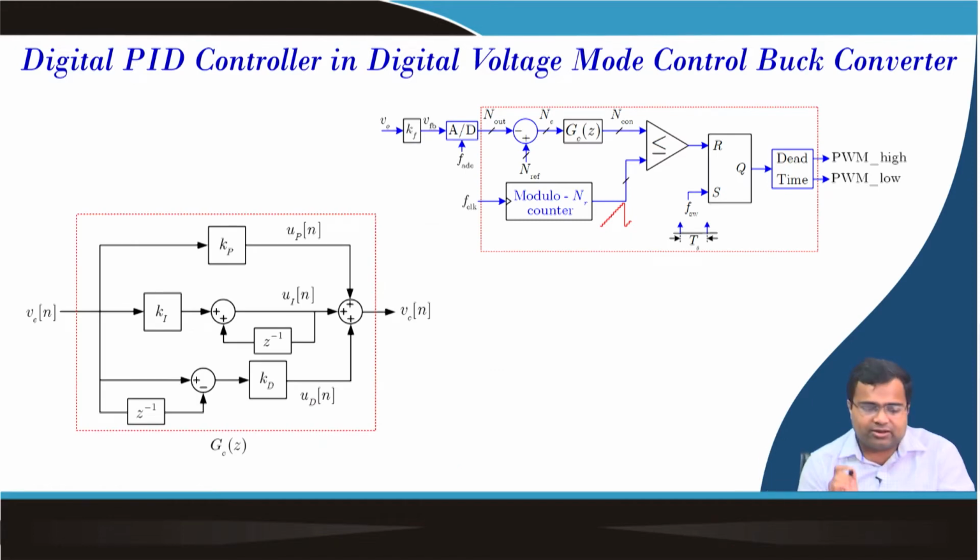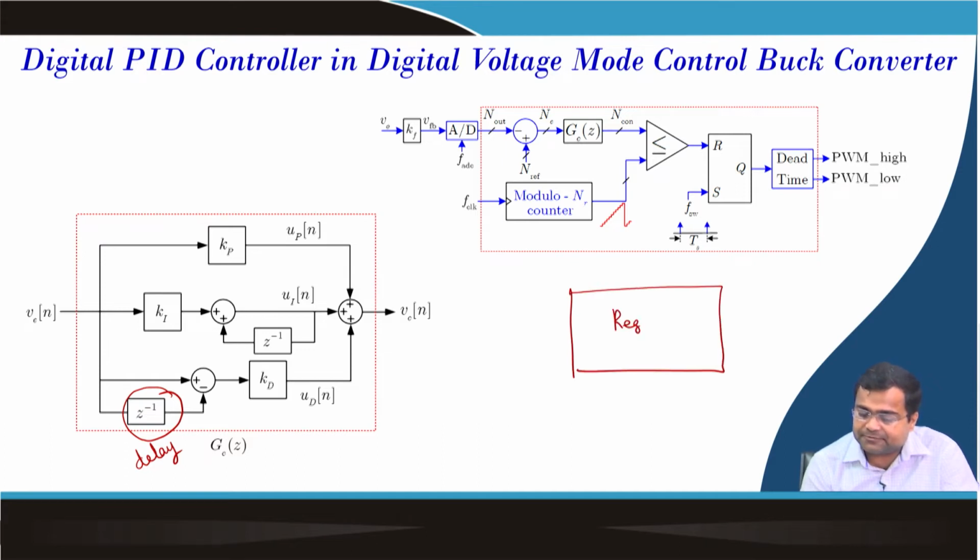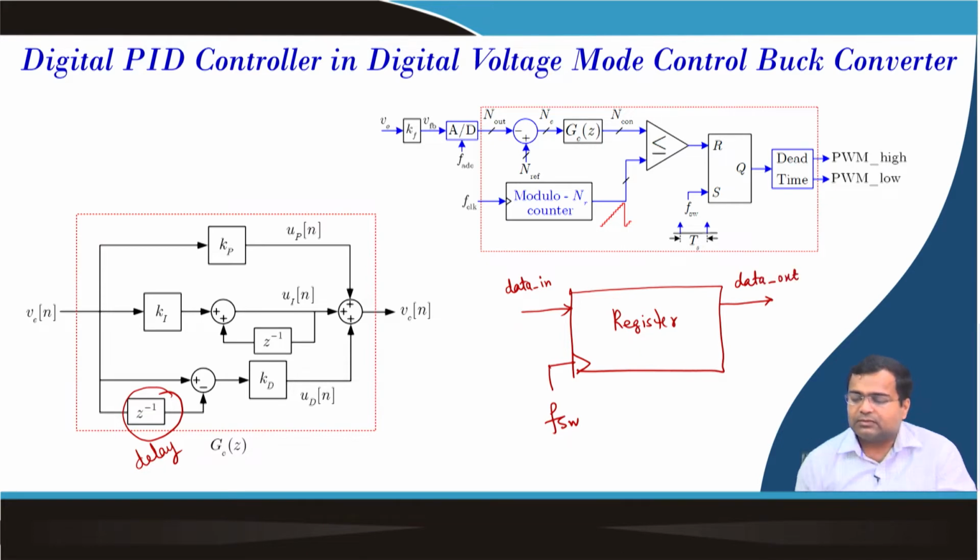This is the overall PID controller simple implementation, we did it in MATLAB. When you say this block, the delay, this delay should again be with respect to the clock, and this we have discussed. This delay is basically a register, and this register will be synchronized with the switching frequency clock, and this register will have a data in. Again, this is vector data, and you will have data out, and the size of the input and output vector data is the same, and the data size will define the size of the register, whether it is an 8-bit register, 6-bit register, 10-bit register, whatever.